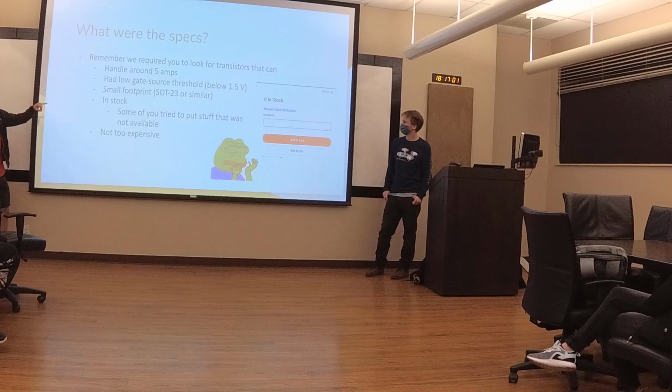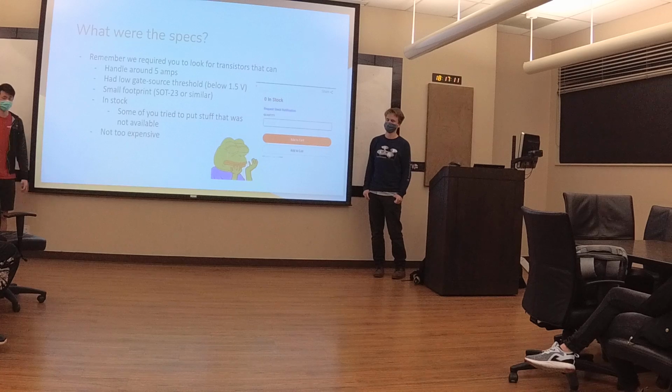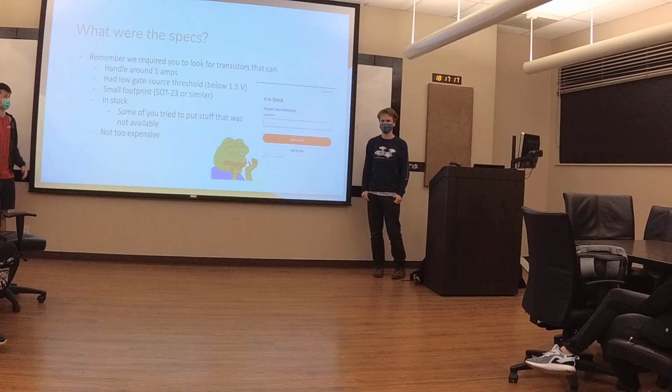So first off, for our transistors, we want them to be able to hold enough current to spin our motors at an adequate speed. We are considering overhead, 5 amps for us, so we already consider having a little bit extra. So 5 amps is what you're looking for. Anything above 5 amps works.